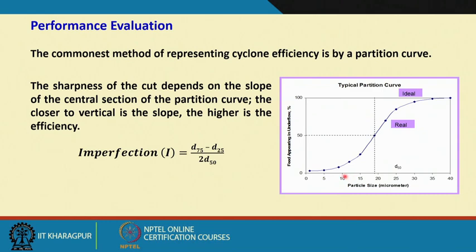Say, suppose in the underflow for a certain fraction from 100 to 90 micron particle, I have recovered 90% of the available material of that size in the feed. So, that is the 90%, and that 90 we plot against the size. For 100 to 90, we take a mean size and plot it at 95 micrometer.